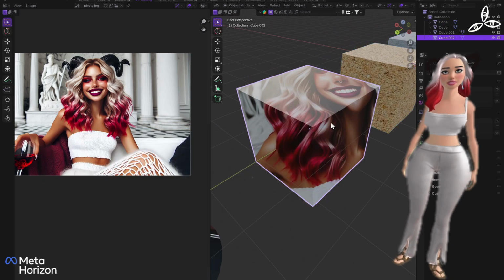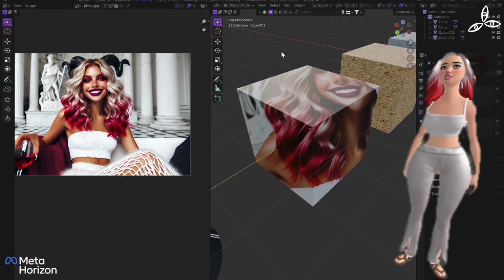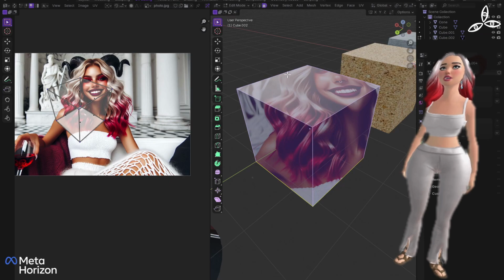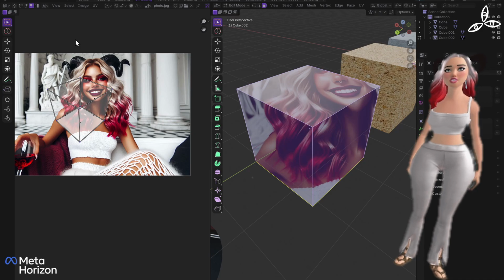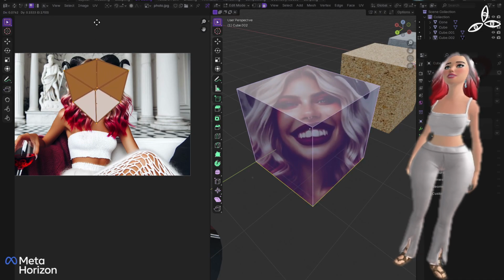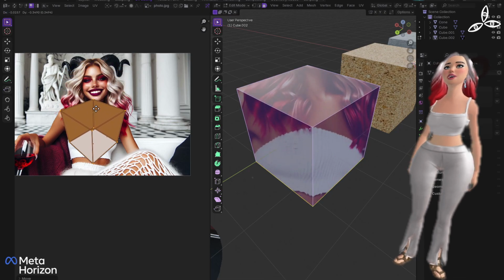So if I go into here again and press Tab and then, oh, hang on, I'm sorry. Tab and then A. I need to make sure I'm in the right section here. So there we go. Tab and A. Okay, and now you can actually see how that projection's happened. Over on this side, if I press A to select all, and G to centralize them, you can kind of see what's going on here.